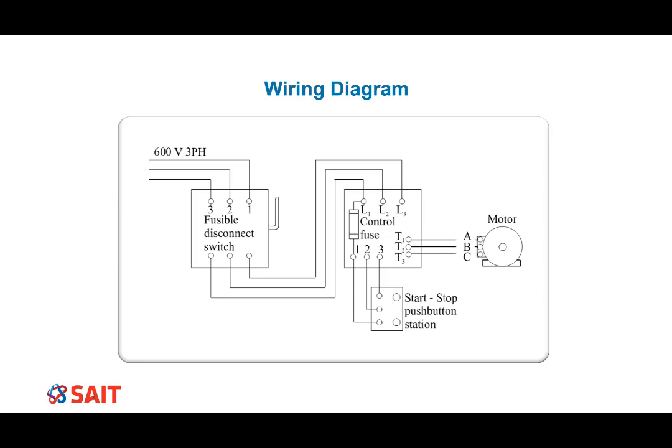A connection or wiring diagram displays the relative physical arrangement of components, including all wiring and connections. The physical relationships and positioning often make it difficult to determine the actual electrical operations and relationships. The wiring diagram shows the physical connections for the schematic diagram. When it comes to the construction of the circuit, the actual equipment layout and wiring should be identical to the wiring blueprint. If it works on paper, it should work in the field, providing the circuit has been constructed exactly as per the wiring diagram.